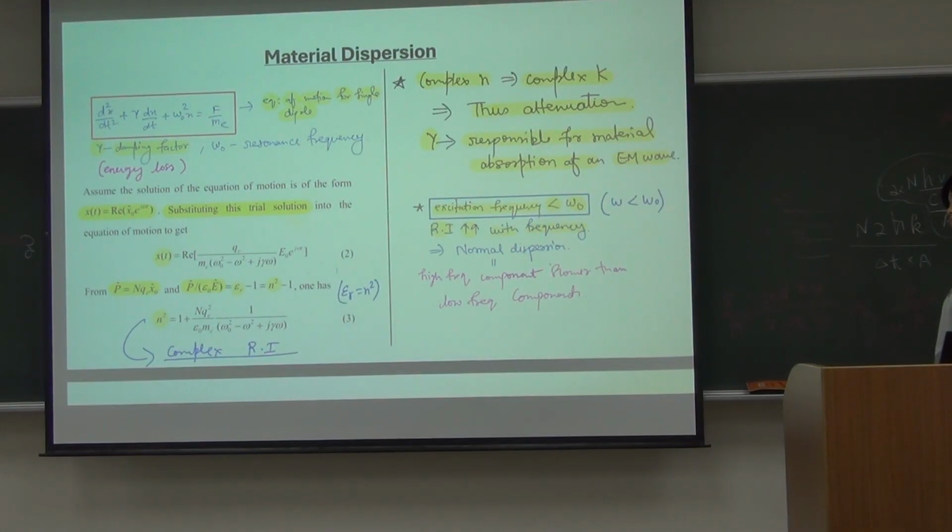Right. So for whatever resonant system, there's a resonant frequency associated with it. If you excite it at the resonant frequency, then the system can strongly absorb the energy. This is my excitation. So if I control my hand to this frequency and feed the energy into the system, it can take the energy very well. Therefore, you get high amplitude in the response.